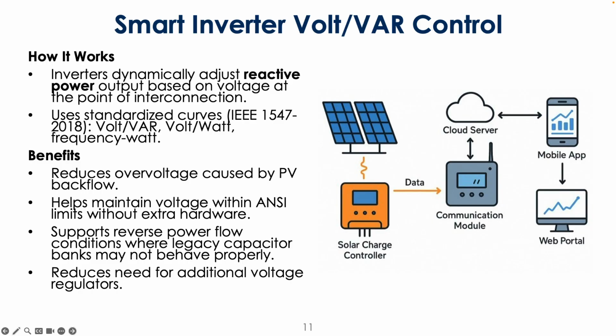This is kind of the odd man out in terms of DERs, right? They do work a little bit differently. We think of this more as support for DER as opposed to what we traditionally think of as flexible loads or distributed generation. One of the things we've talked about with rooftop solar that injects power back onto the grid is that you might have some voltage issues.